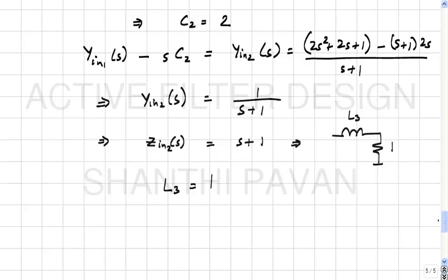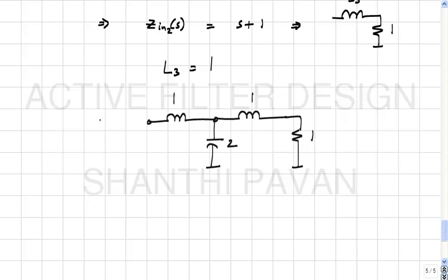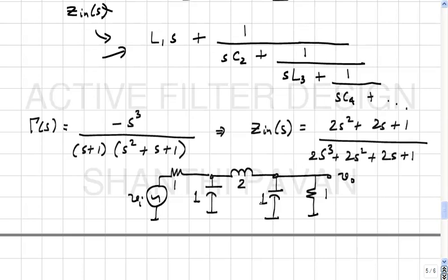Okay. So the LC network that results in a transfer function which is a third order Butterworth: this is 1, this is 1, this is 2, this is 1 ohm. Yes, sir. No, but at DC, the magnitude is half if you have both equal terminations, isn't it?